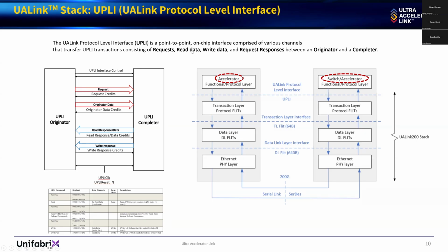UPLI is a point-to-point on-chip interface that is comprised of various channels. Here we can see the channels: request channel, originator data, read response data channel, write response. And UPLI is the actual protocol format that powers UALink and does the operations that we talked about. If we look at the command set, and this is part of the command set, you can find the whole command set at the UALink specification.